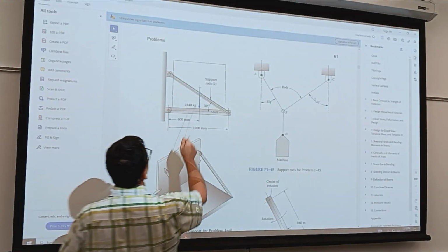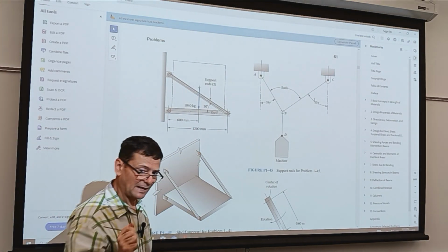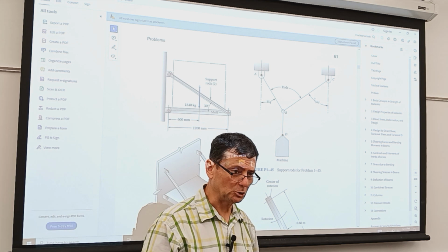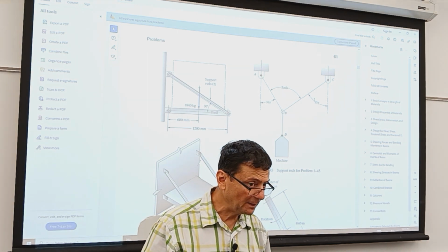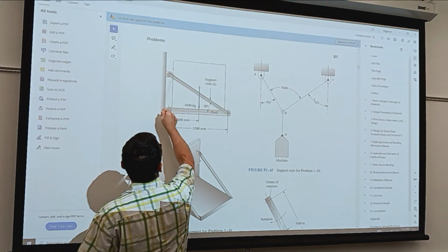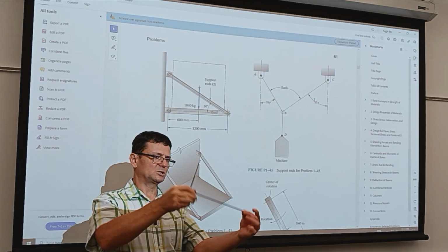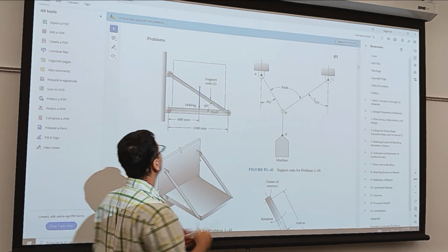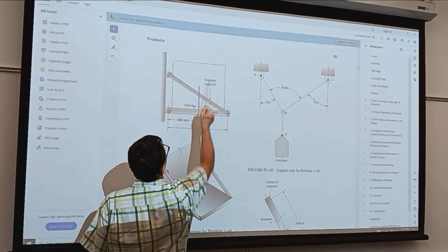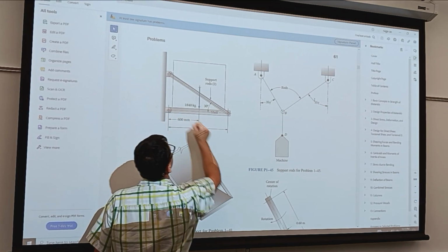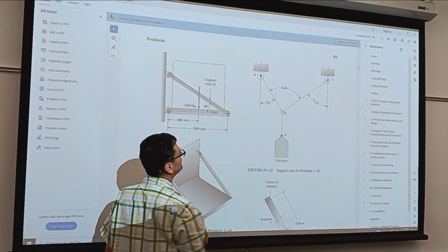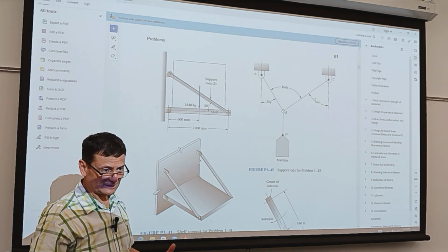This also, we know it from statics. Do you remember its name? The two-force member rings a bell. So this is a two-force member. However, this is not. It's a two-force member wherein it's subject to just tension. And when you see pins at the end and a force that is other than in line with the axis of the beam, that's no longer a two-force member.